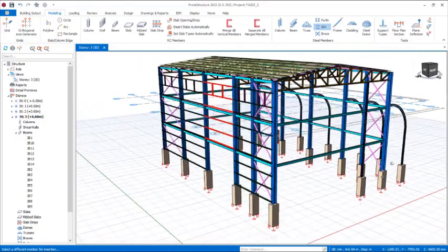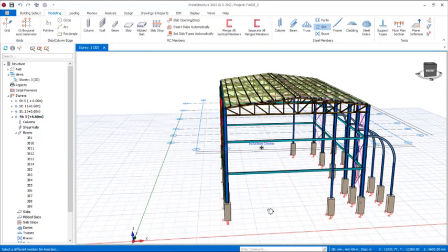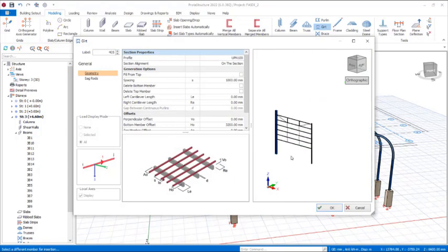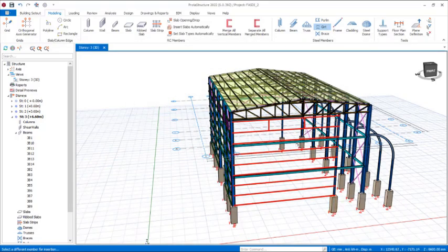All right, so over here we'll also be having these small provisions as an entrance, so we'll be placing a gate here as well. So pick these columns right there, and then pick this one right there. So you have this with that offset that you have inputted. So at this time we are going to remove the offset, change it to 200. Okay, get it like this, just 200 right there. Click on the OK option to have it just like this.